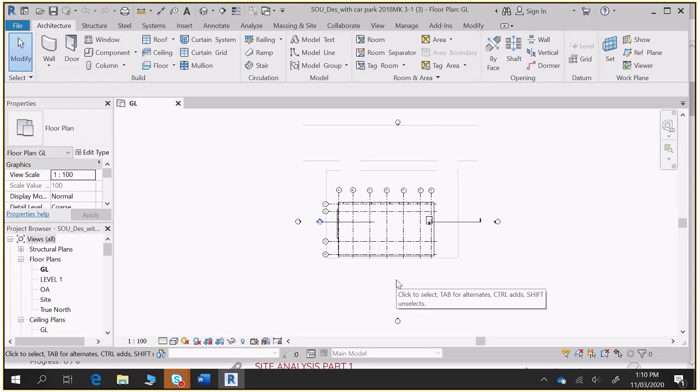All of these new standards and requirements end up making conversion of properties into residences more difficult as we go on. Take the requirement for a vapor-proof membrane underneath a slab. That means you can't just get an old factory and decide to make it a residence, because there's no vapor-proof membrane under the slab, unless you have an engineered response to meet the NCC. That's sort of what we're dealing with here.